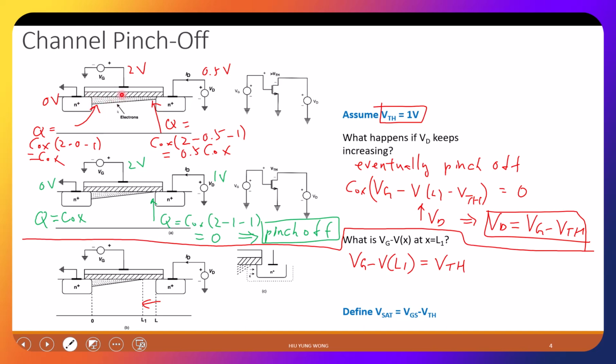So this is a transistor, right? We have three terminals. This is source, this is gate, this is drain, and this is NMOS because the source and drain are N-type. The substrate has to be P-type, right? P-type means that you have a lot of holes. Before we apply a gate voltage, you have NPN, or back-to-back NP diode. It's not going to conduct. It is an off state. This is a first order analysis.